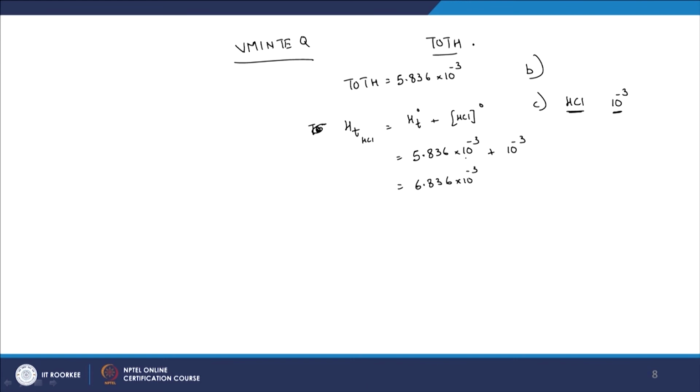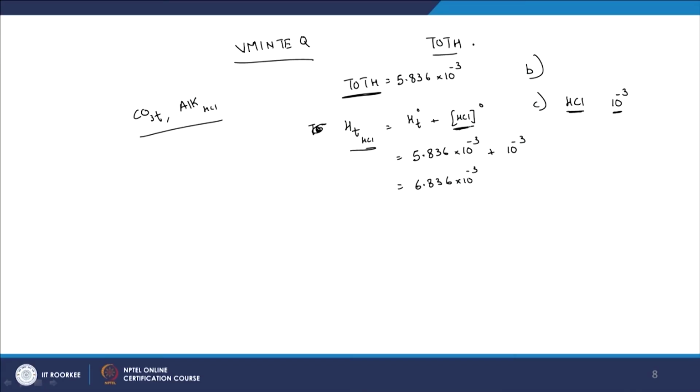So, again earlier we looked at it with respect to CO3 total and alkalinity, right, after addition of HCl. Another way to calculate by hand is to look at the effect on total H, and how is that? So, how are you affecting H total here? You are only adding acid, which is going to be affected by increase in H plus. So, that is why H total after addition of HCl is going to be equal to H total initially plus the concentration of strong acid that you are plugging in. Strong acid meaning I am assuming that all the acid is going to dissociate. So, all the H plus is going to be donated and stay in the solution. So, that is why I have HCl here, and with that I now have H total given here.